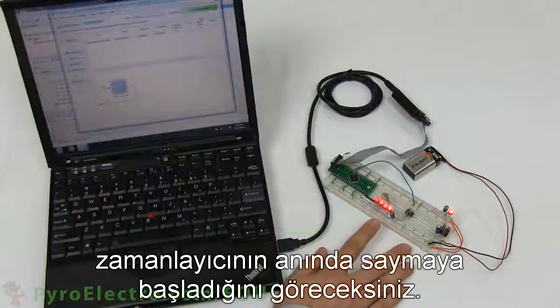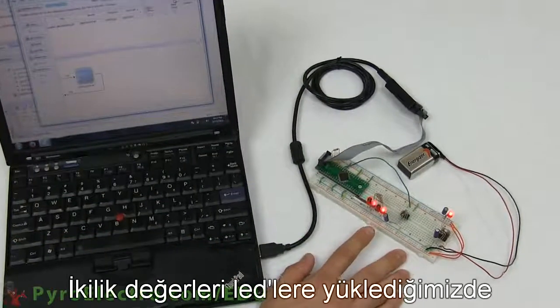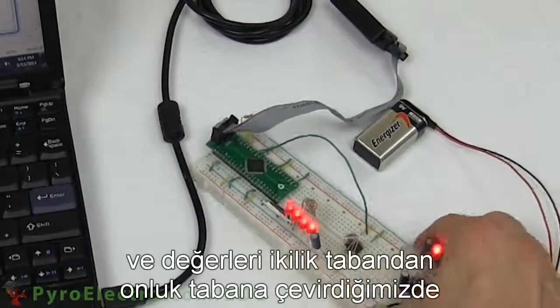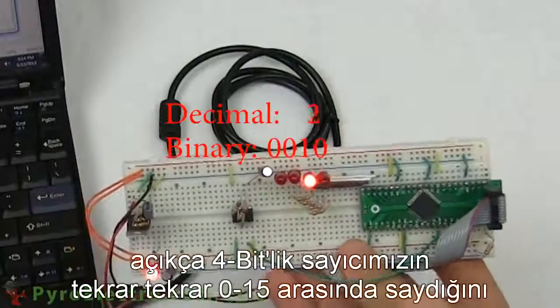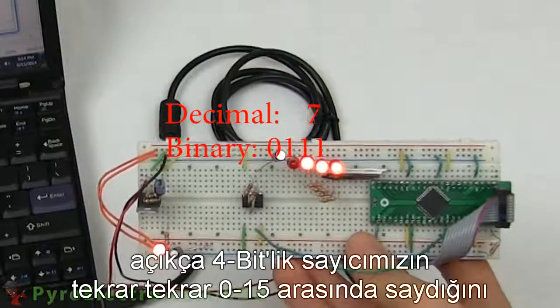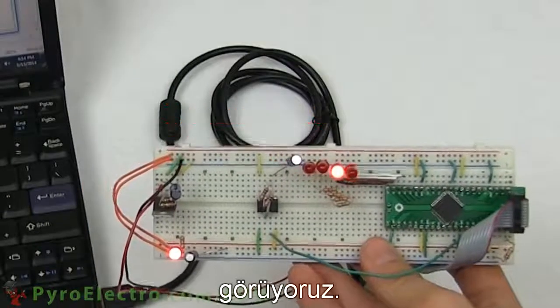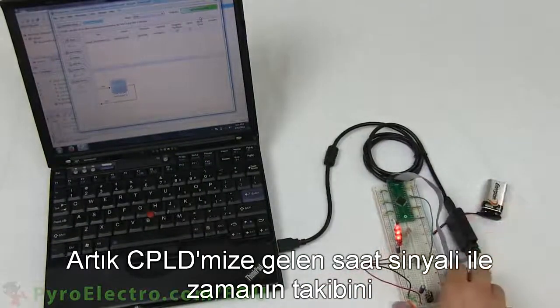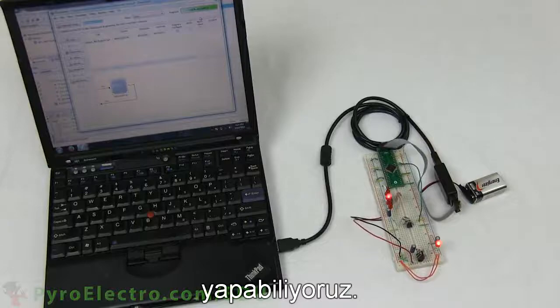Right away, you can see the timers beginning to count. If we overlay the binary values above the LEDs and convert them from binary numbers into decimal numbers, it's very obvious that our 4-bit counter simply counts from 0 to 15 over and over again. So hooray! Now we know how to keep track of timing using a clock input signal to our CPLD.